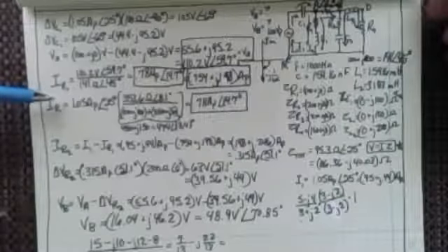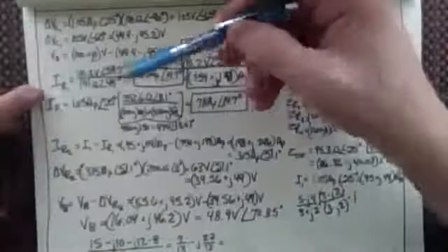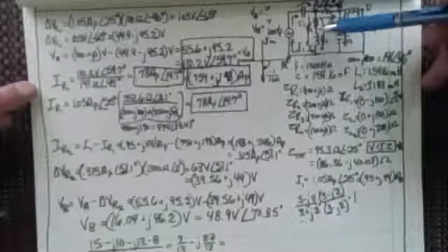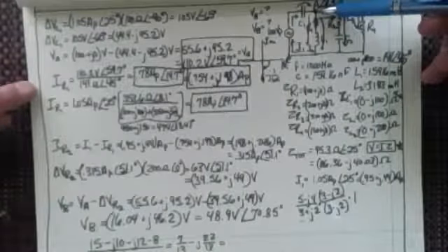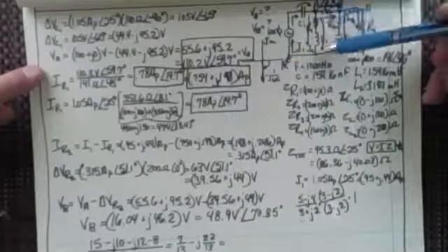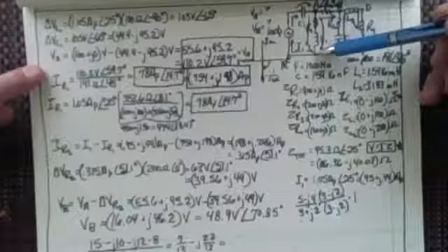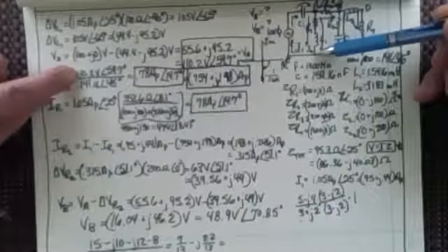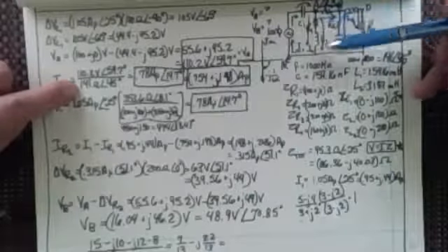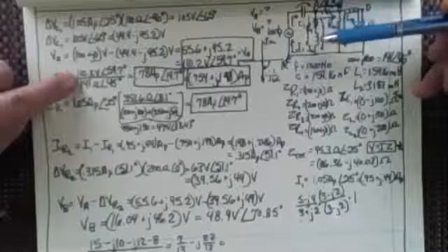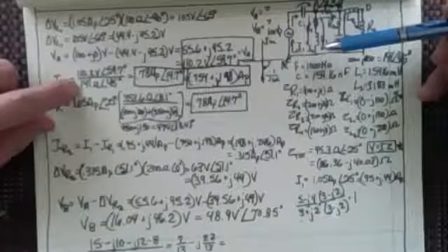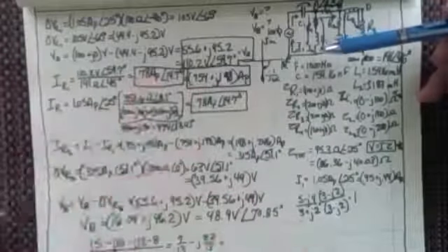what I did. Now, the first thing that I did, of course, up here was I just took the voltage across that impedance branch, right? Because this one is 110 volts up here, 110.2 volts at 59.7 degrees, and then 0 volts at 0 degrees down here. So I knew that that was the voltage difference. And then I also knew that this branch of the circuit had a resistor and an inductor that had a combined impedance of 141 at 45. And of course, that's how I got this. And everybody was here when I did that.